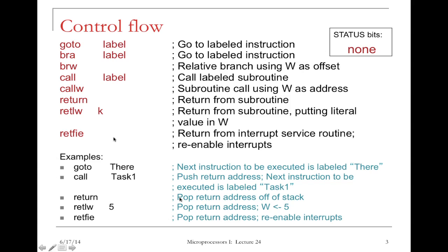The RETURN instruction is the last instruction you need to use in the subroutine. And this instruction will pop the return address off the stack. This is the opposite of the call instruction. It will get the return address out of the stack and use that return address as the next instruction to execute.